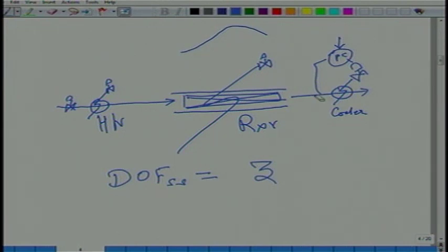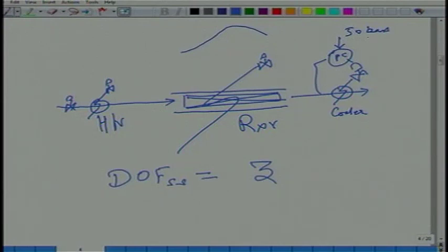If this pressure is increasing, except for the pressure drop across the reactor, this pressure is also increasing, right? So if this pressure set point is 50 bars, for example, and I make it 60 bars, I guarantee you the pressure inside the reactor has also gone up, save for the pressure drop through the reactor.